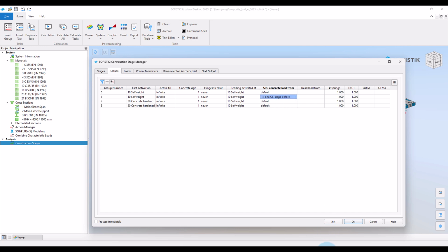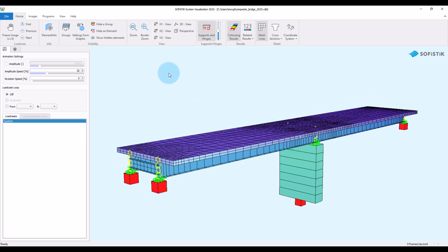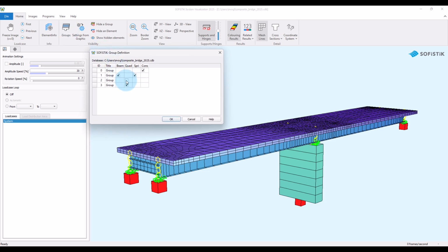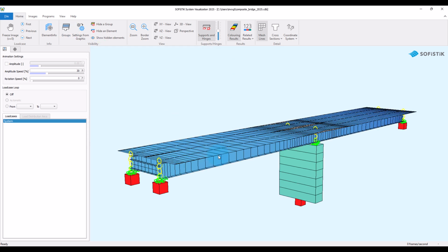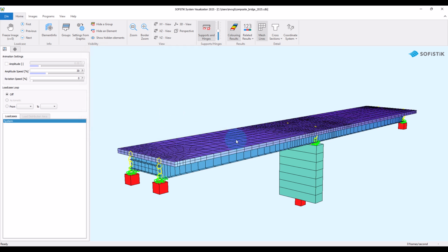Now, as you know from modeling the system, we are activating beam elements which represent the complete composite section, including the concrete slab, and we also have area elements which also represent the concrete slab. Now you might already wonder if we do not account for the slab twice in our analysis. As you might remember, we handled this topic for the self-weight by assigning the area elements a concrete material with zero weight. The topic of the stiffness we will treat now.